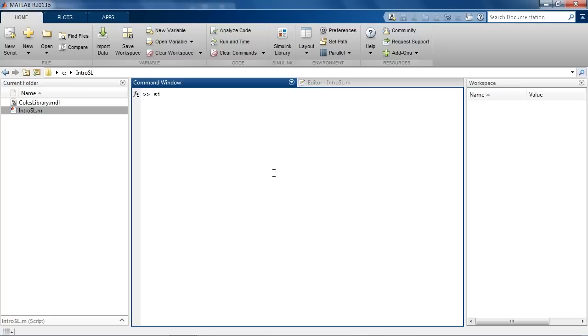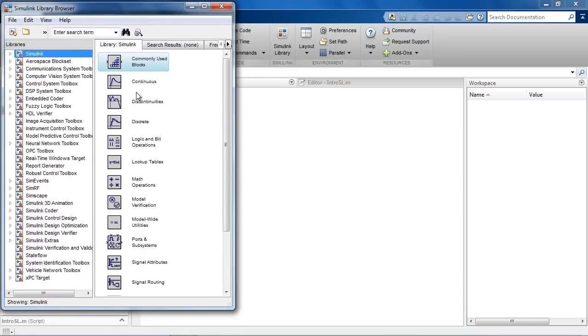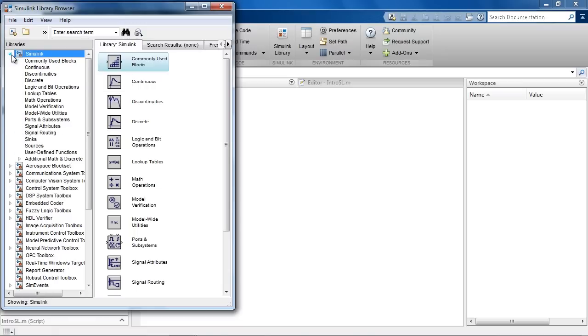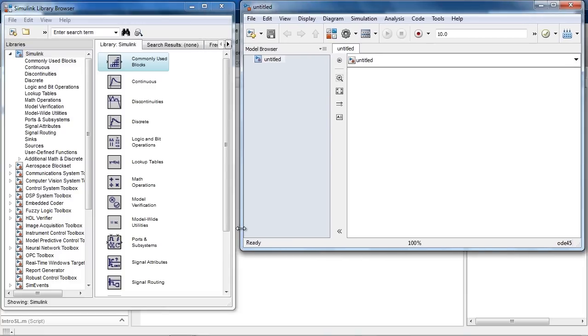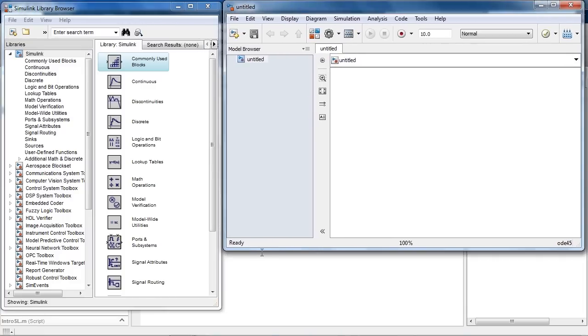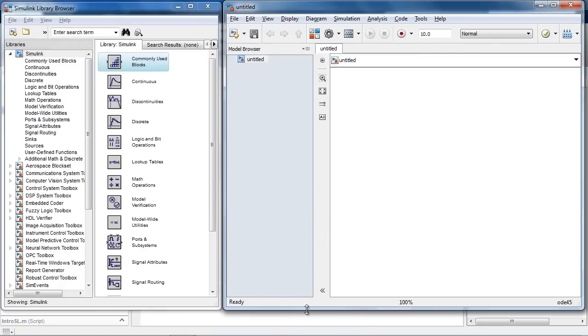And the way I like to do that is by typing in Simulink in the command window, but there's actually other ways to do that. What's your preferred method? I probably type in Simulink a lot. Sometimes I just open up an existing model, or I'll click on that Simulink library button up there. This button right here. Open up the Simulink library. So typing it in or clicking on this button will do the same thing, but as a longtime Simulink user, I tend to just like to type it in. Probably also because I like MATLAB and I type a lot of things in MATLAB. Yeah. That could be another reason why I like to do it that way. When you're an avid MATLAB user, you tend to use the command window quite a bit.